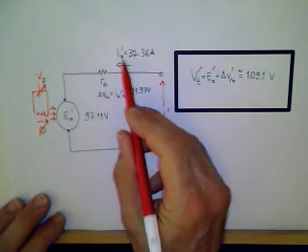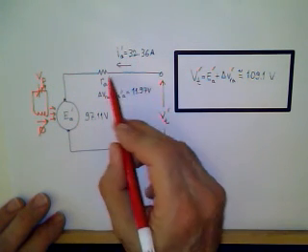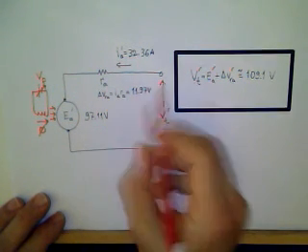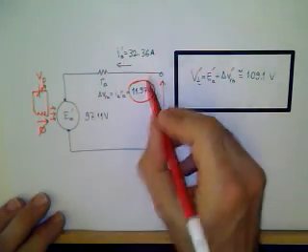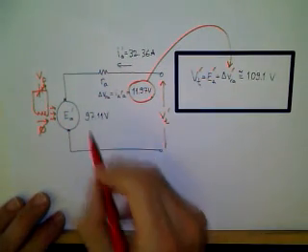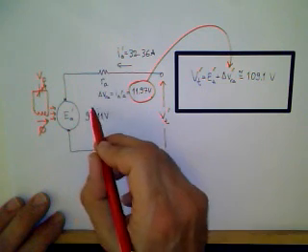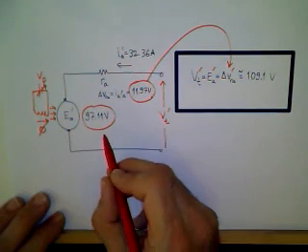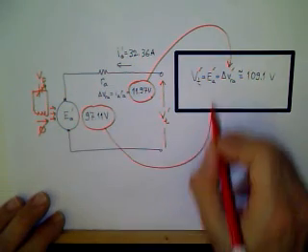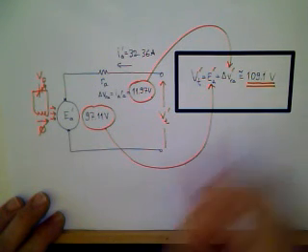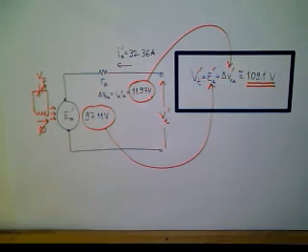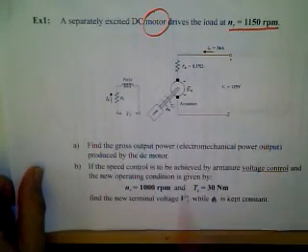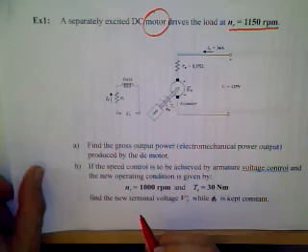Yeah, we do have armature current of 32.36 amperes across 0.37 ohm resistor, which results in a voltage drop of 11.97 volts. So this is substituted here, and from the speed ratio we had calculated the induced voltage as 97.11 volts, and we substitute there. So we end up with a new terminal voltage of 109.1 volts. So this concludes the solution of our problem given in the lecture slides and in the lecture notes.